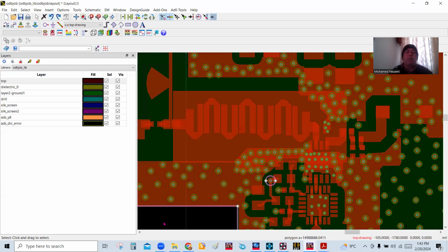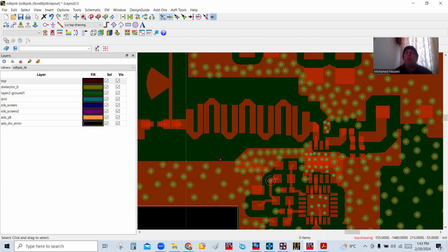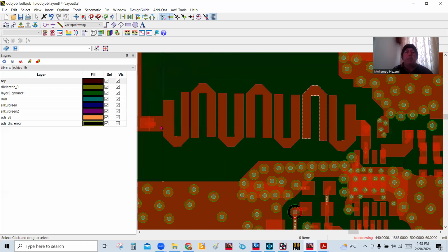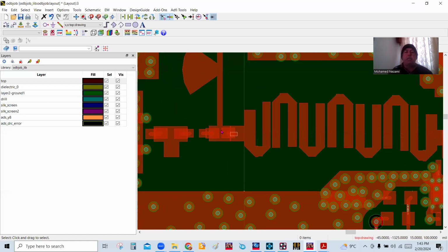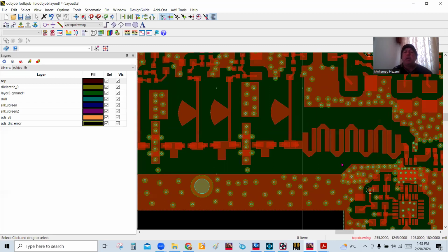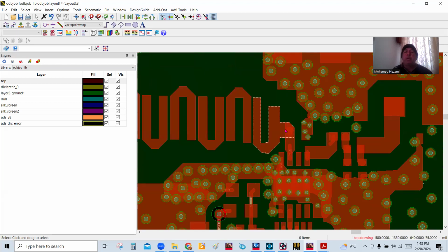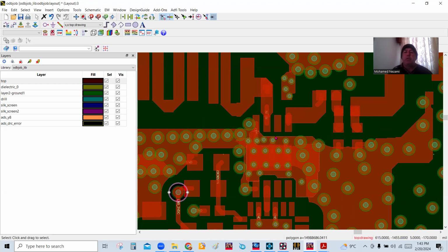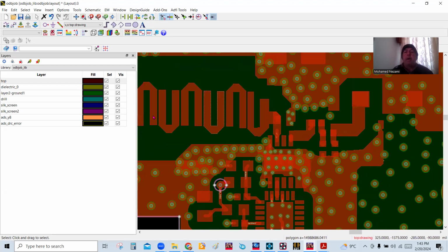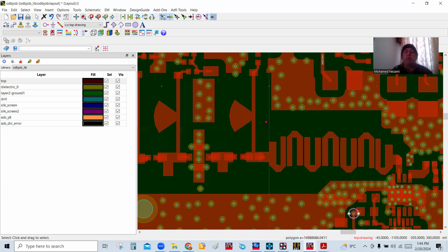So basically, okay. And that's critical because we want to do that before this board is sent to fab layout so that we can avoid any issues. Because when you bring in this filter, you have to extend the input and output. For instance, in this case, I had to connect this filter to the last stage LNA, okay? And then I also had to add more copper work to get it into the QFN mixer in here. So I wanted to make sure what impact that had on the filter. We want to make sure this filter is okay before we send it out to fab, because once we do that, that's very expensive. So today, let's do something more.